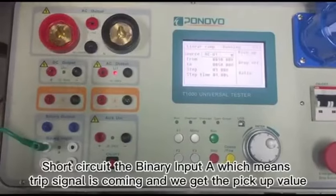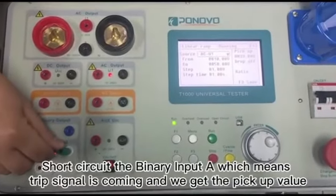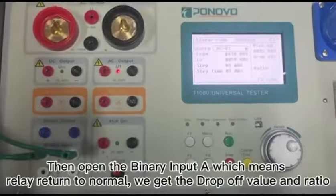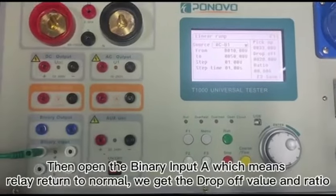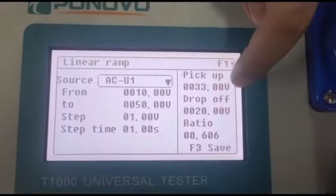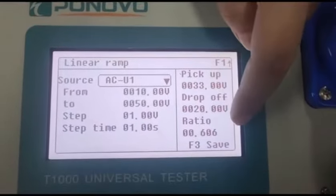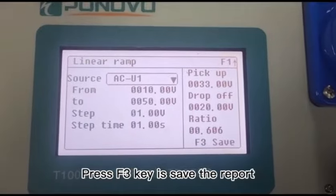Short circuit the binary input A, which means trip signal is coming, and we get the pickup value. Then open the binary input A, which means relay return to normal, we get the drop off value and ratio. Ratio is the drop off value divided by pickup value. Press F3 key as save the report.